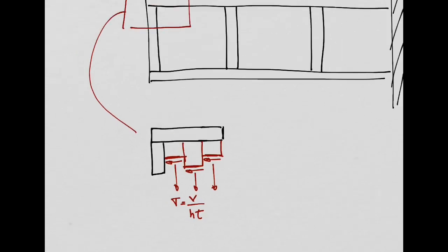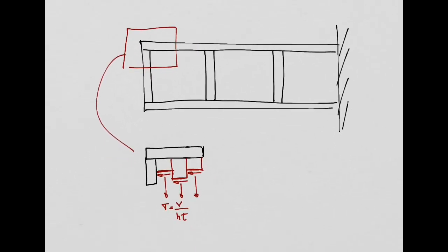And we have something more else. So imagine I am doing, like you did in year 1, I'm cutting. So this thing here, it means I am cutting part of my spar, this part inside this box, and I'm analyzing that. So what did I cut? Well, I did cut the web here, and I did cut the post as well, right? So before I cut the post, I need to include a force in the post, force in the post, FP. And I'm assuming that force in the post is going to be compressive. Yeah? Okay?